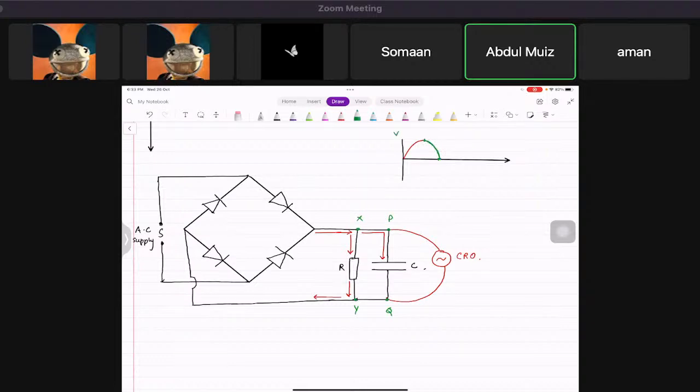Yeah. So the voltage is basically increased to a point, and because it was an AC wave, it starts dropping here, and when it starts dropping, the charged capacitor then provides current to the resistor, so that during this drop, the capacitor has given current to the resistor so that it can fill this gap where it was required.